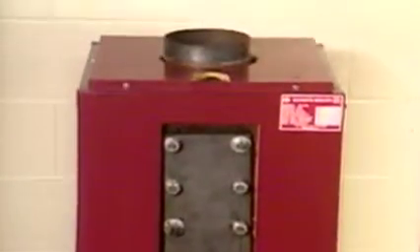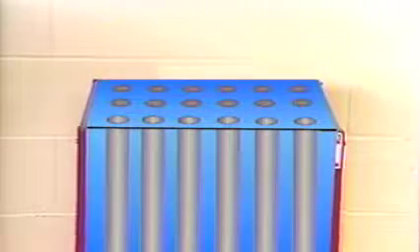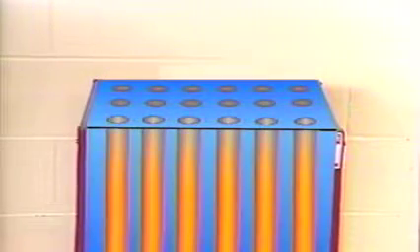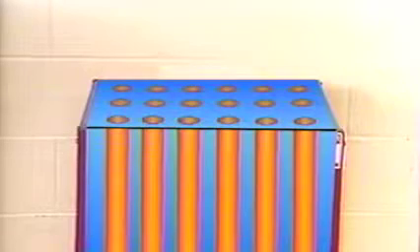This is a dry base boiler. The combustion chamber totally surrounds the flame. Oil droplets are completely burned within the chamber. Hot gases exit at the top to give up their heat to the surrounding heat exchanger surfaces.